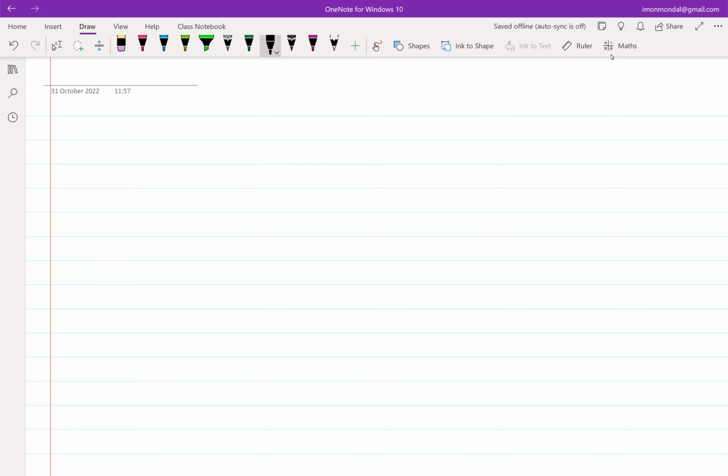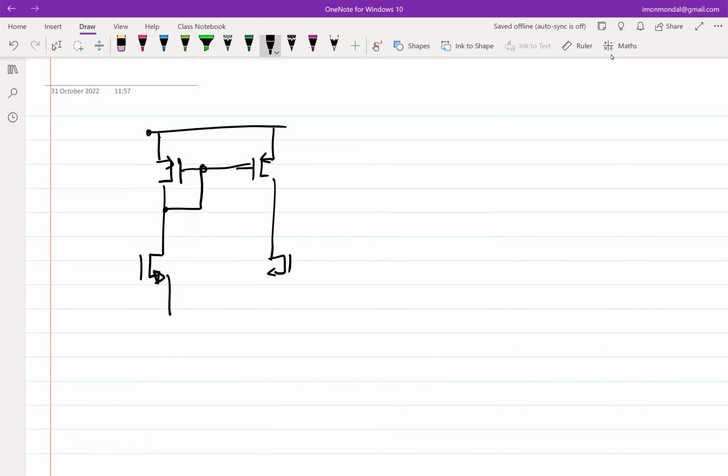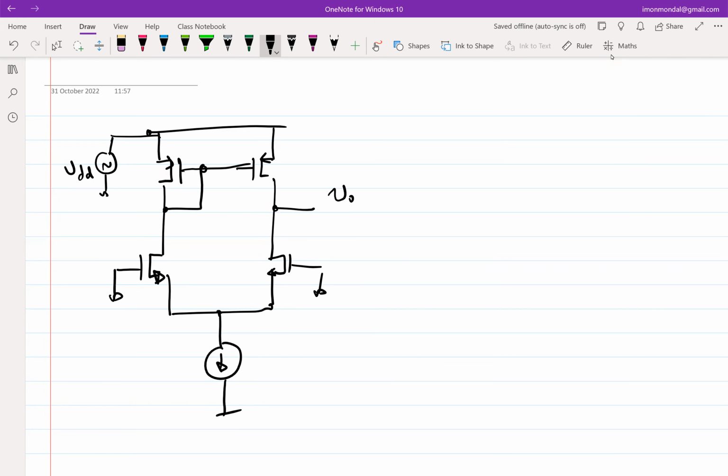So when we were discussing PSRR in the last class, we saw that the definition of PSRR is essentially this: if you have a small signal excitation at the VDD, that is the PSRR plus, then in the open loop configuration, you figure out the incremental V out, that is V out by VDD, and divide it by the differential gain, the open loop gain.